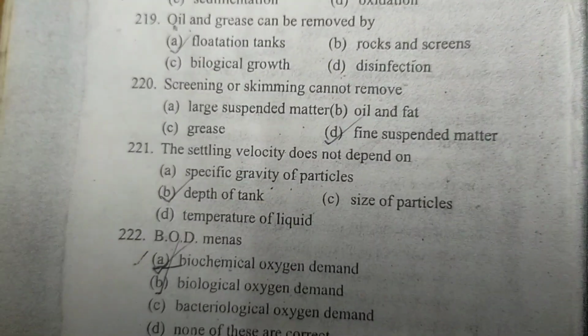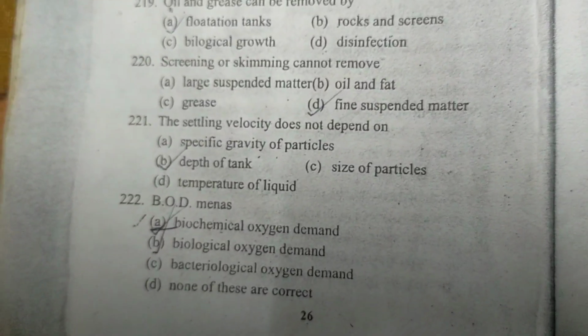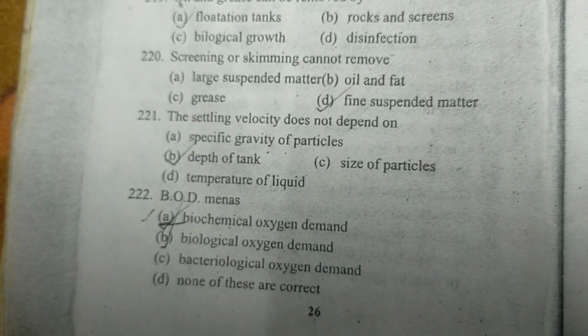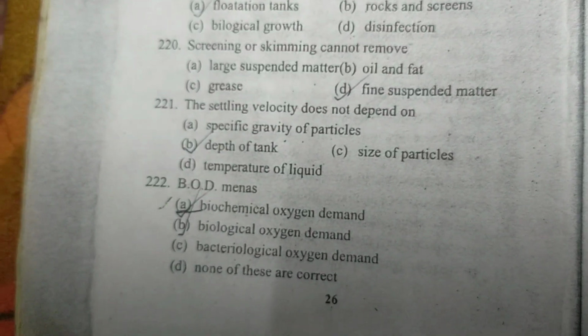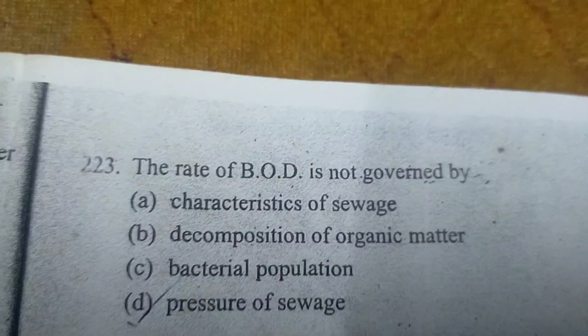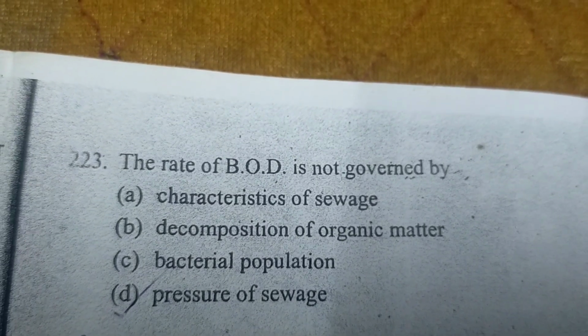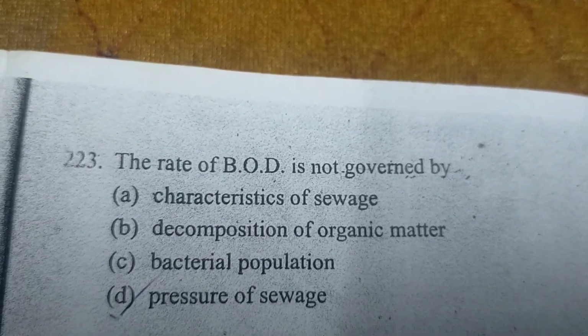Screening or skimming cannot remove fine suspended matter. The settling velocity does not depend on depth of tank. BOD means biological oxygen demand. The rate of biological oxygen demand is not governed by pressure of sewage.